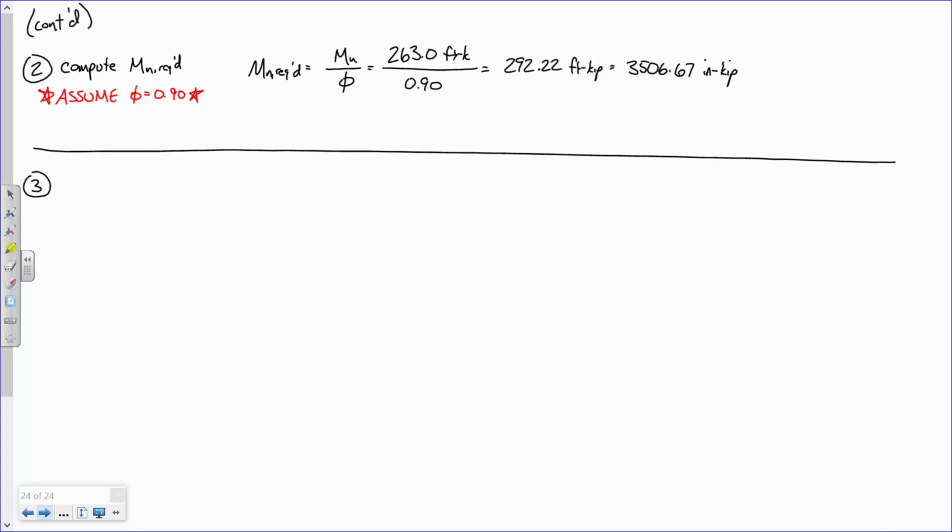Now what's step 3? There you go. So we're assuming a rectangular beam, and using that assumption, what are we computing? Well, ultimately, but what do we calculate in between? Rho. So we're computing required rho. And then we assume essentially what Mr. Fitzpatrick said, a rectangular T-beam.